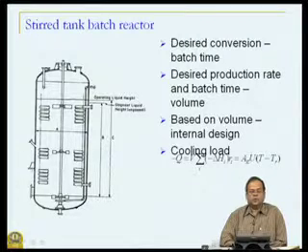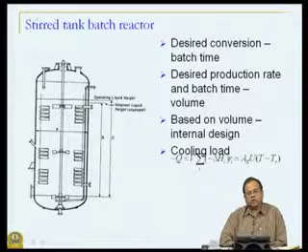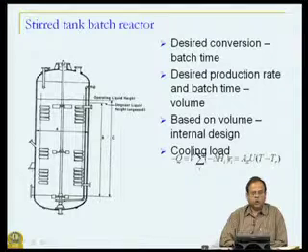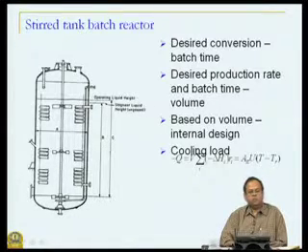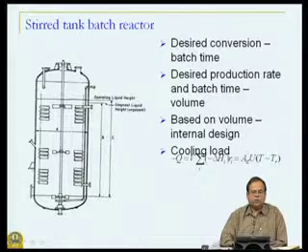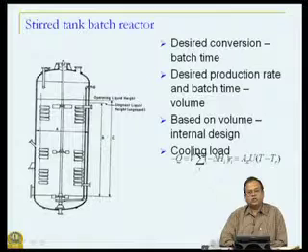The mass transfer aspect is represented by assuming the resistance to mass transfer along the thin film which surrounds the interface, particularly on the liquid side between gas and liquid, and once again on the liquid side between liquid and solid, and doing certain manipulations such as steady state assumption and so on, we come up with the mass transfer rates, and couple it with the kinetics. So, now let us try to design this reactor.